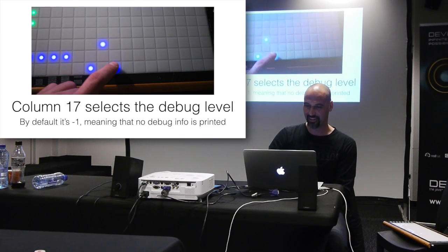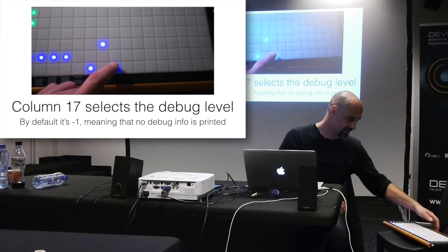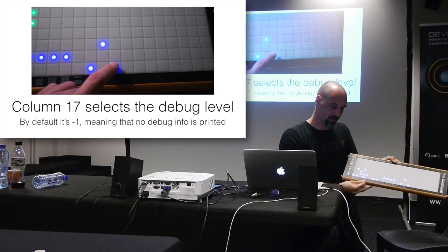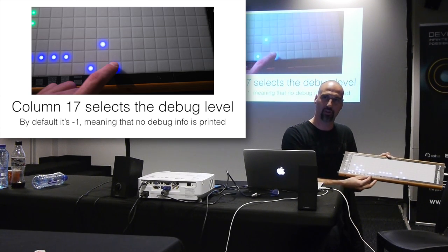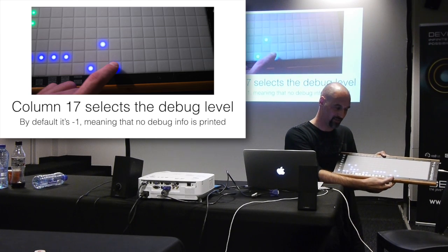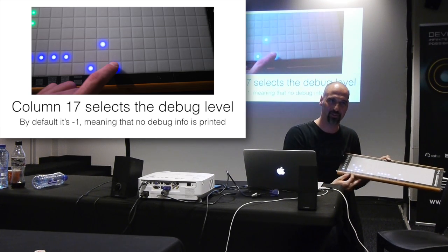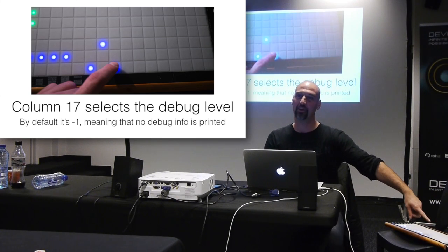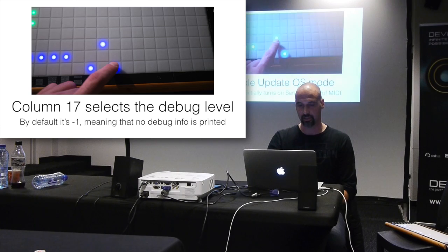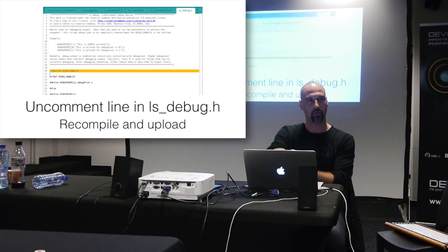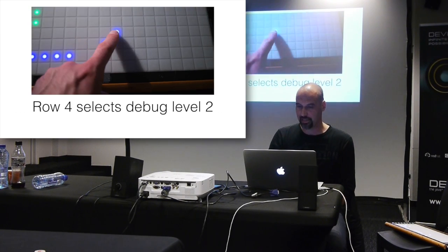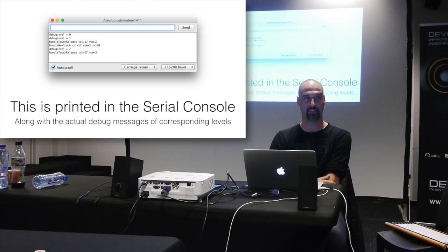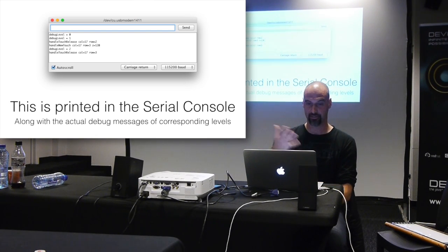Do you have any marks on the sensors so that you know which are which? We've got these user functionalities, and it's the column right next to the ones that everyone uses. That's the one for debugging. But it's only going to be active if you activate a debug mode here. Otherwise, that column is not going to be active. And then it's going to display like this. So you're going to get in your serial monitor: okay, debug level has been activated. This is what's happening. I had a touch. These are the values, and so on.